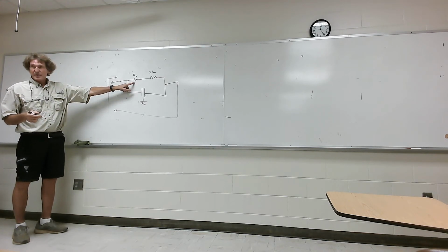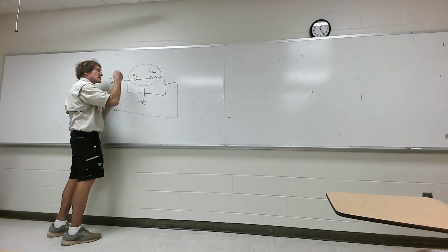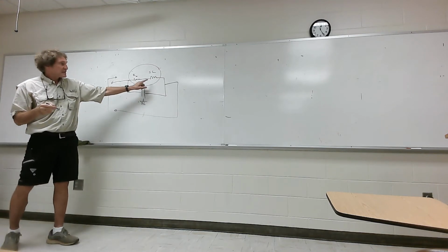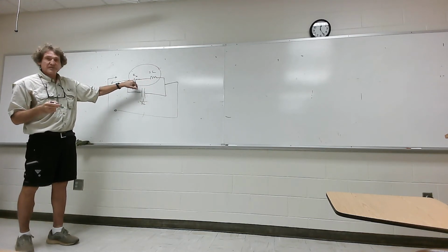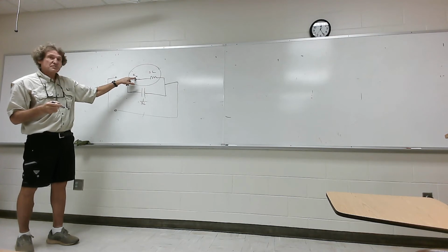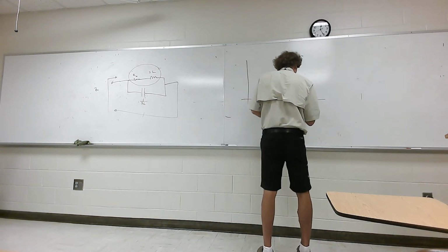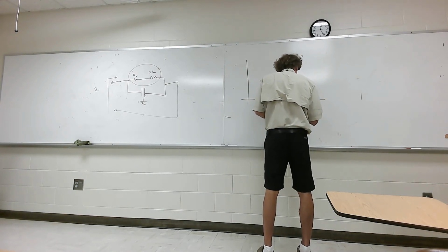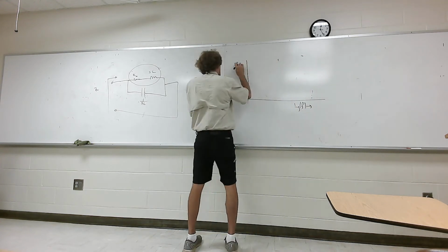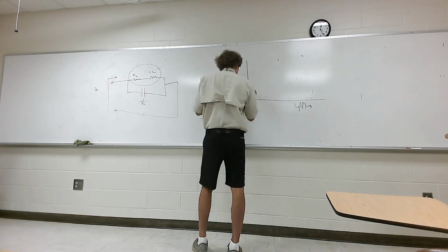You all follow me? All right, as you get higher and higher frequencies, the first thing that actually turns on is that circuit. All of a sudden, this inductive reactance is going to be greater than this resistance. And the point that it kicks in at is when SL is equal to this in magnitude R. That's your first break frequency. So when you're plotting the impedance in a Bode plot form, versus the log of the frequency here, and 20 times the log of Z here,